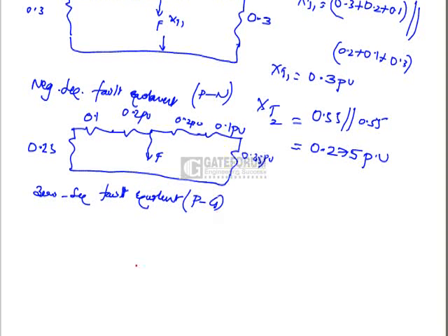Now since we have star grounded, this is, let us take as ground equivalent, ground point, whereas these two are neutral and neutral. Okay, now we have to draw, since it's star grounded, we can ground this one. And what about the zero sequence reactance for the generator, which is equivalent to 0.2.